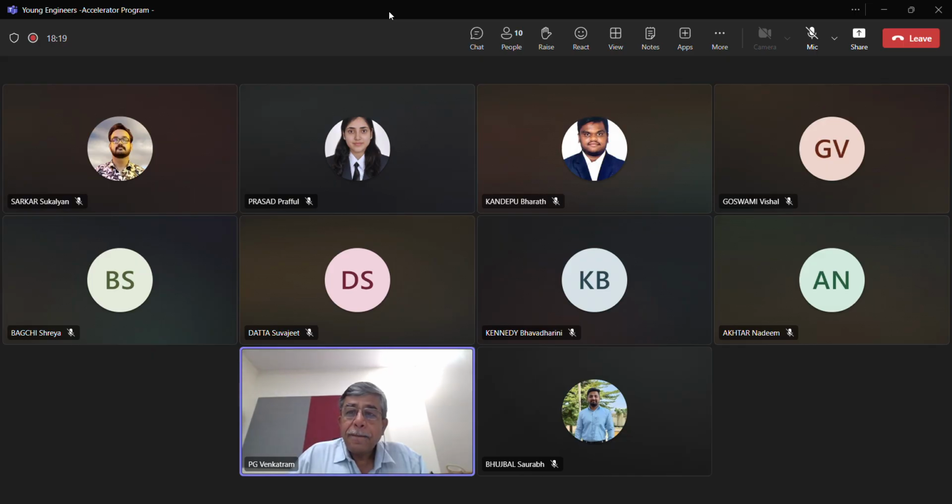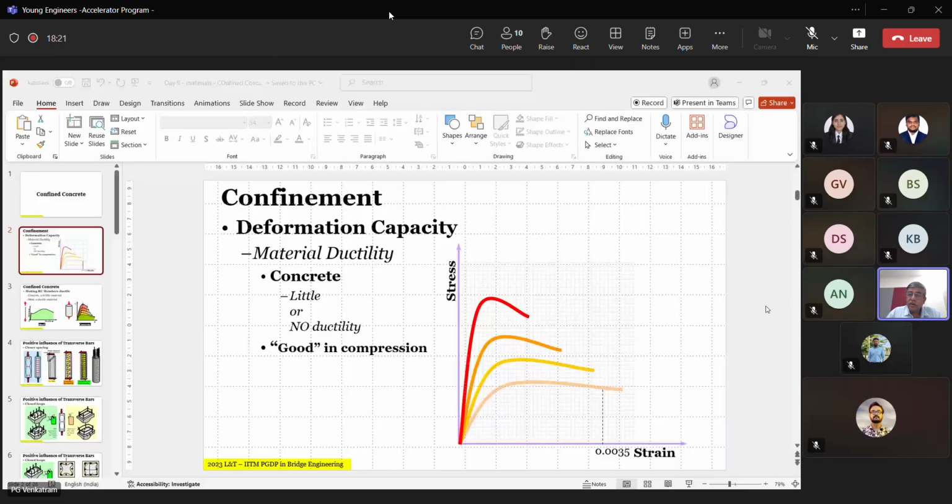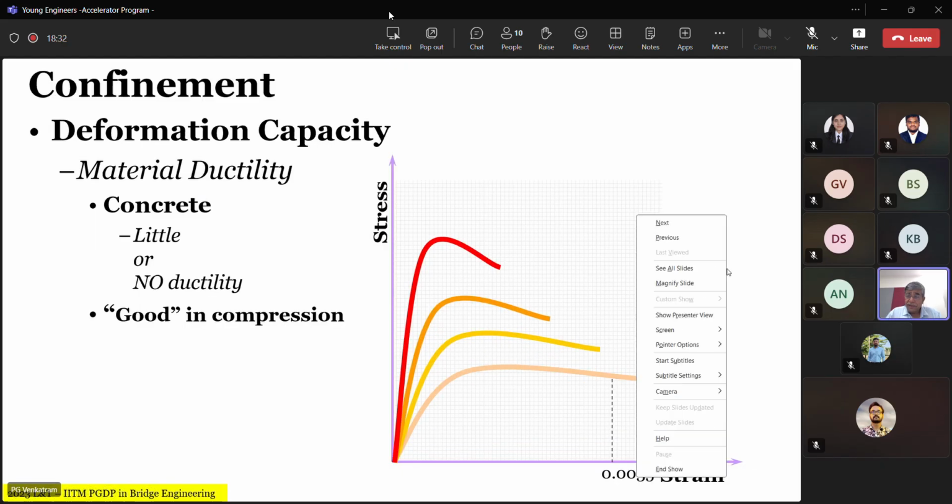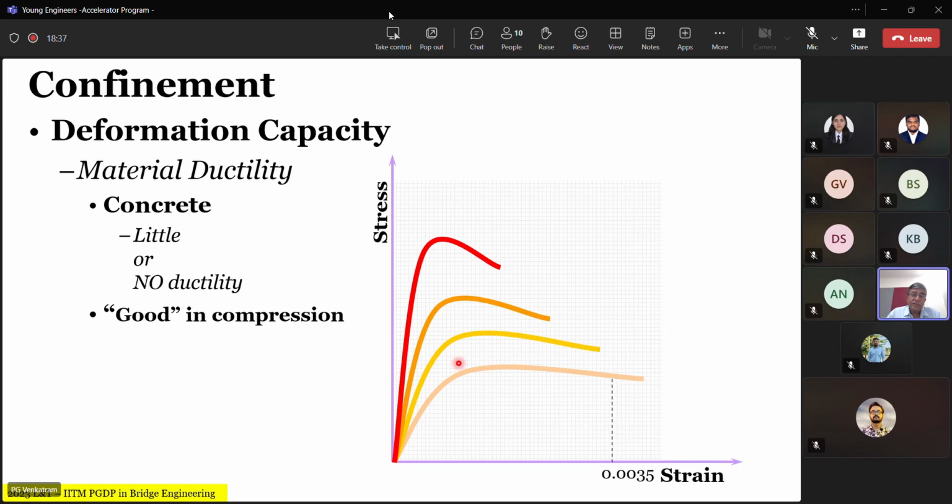What we were seeing is that concrete as a material is practically not ductile compared to steel. But nevertheless, it has some amount of internal ductility from the classical definition of the ratio of epsilon cu by epsilon y. Now, the question I asked you was about this 0.0035 that we talk about. In reality, is this the value? Can concrete not take strain more than this?